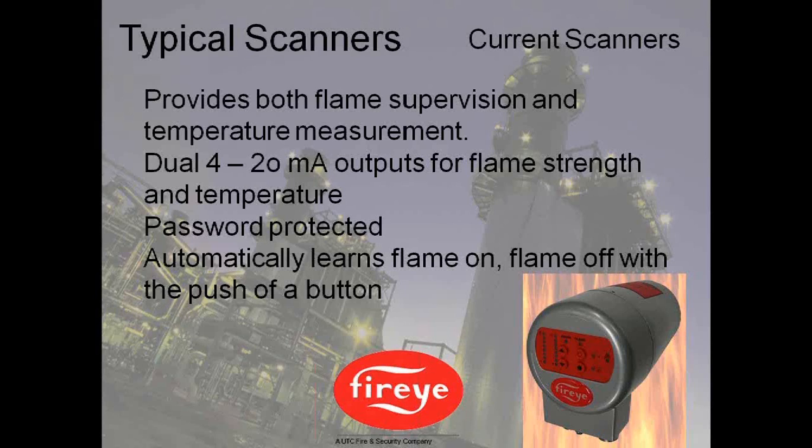If you've got a utility boiler that may have 24, 48 burners in it, pulverized coal, there's no way you can use oxygen to know which burner is going out of ratio. So when the burner is initially set up, we find the flame temperature. If that burner starts to drift, we're able to make corrective action and pinpoint which burner is drifting. Applications for this might be a power generation plant where maybe you've got 3 decks, 24 burners, coal-fired. You can't really use oxygen to know which burner is going out of ratio, but if you sight it for temperature at optimum ratio, then you get an indication.